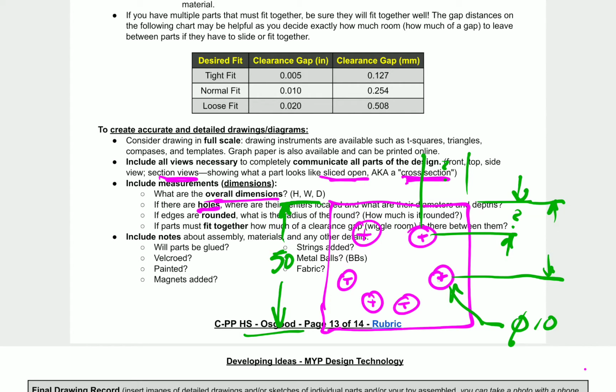You better not tell me that the center of that hole is 60 millimeters from that edge, because otherwise it would be down here. That hole would be off of the 50 millimeter opening. So it's a little bit of math, but it's applied math. It's real math. You're really trying to figure stuff out.